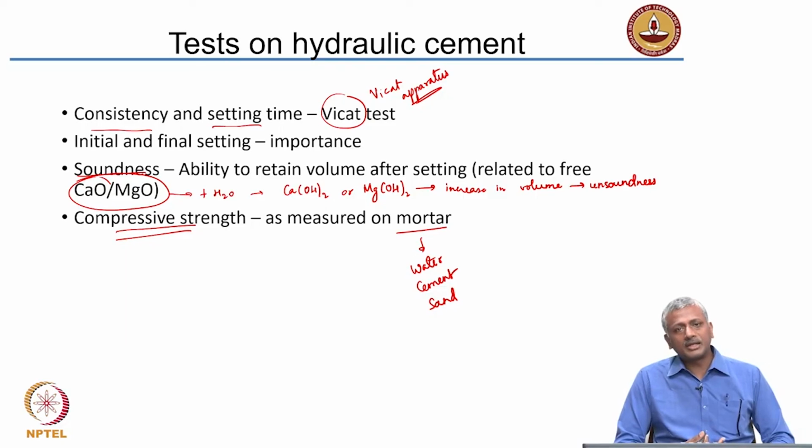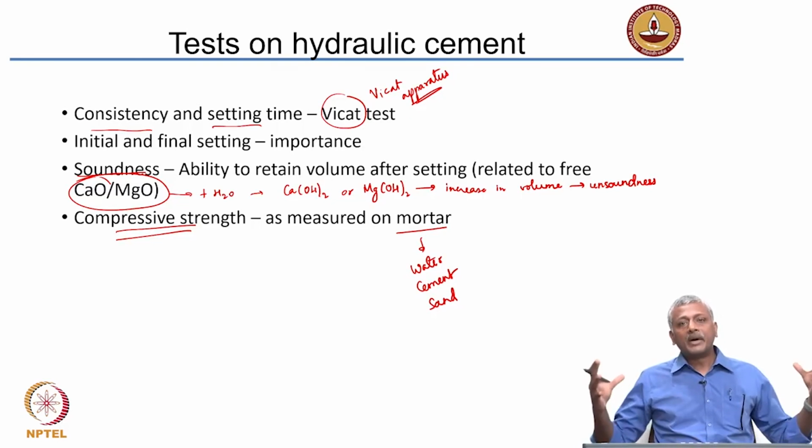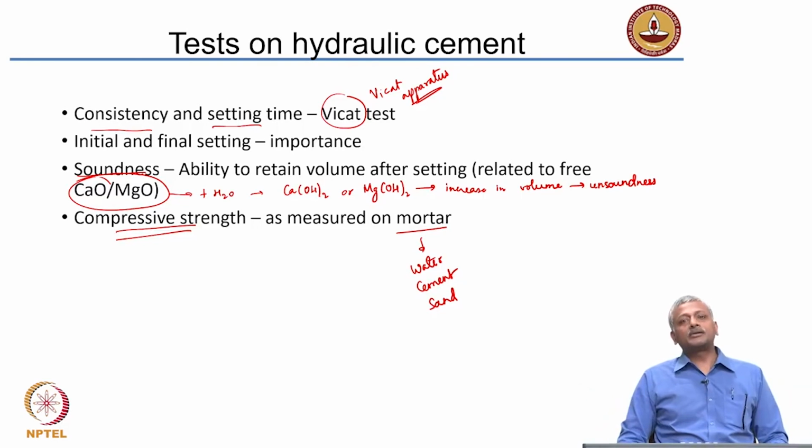It is something that you should think about. The whole point of the matter is, cement does not function as a strength giving component on its own. It basically provides strength by binding the aggregate particles together in a concrete. That is why we want to test the strength of the cement with respect to its nature of binding.